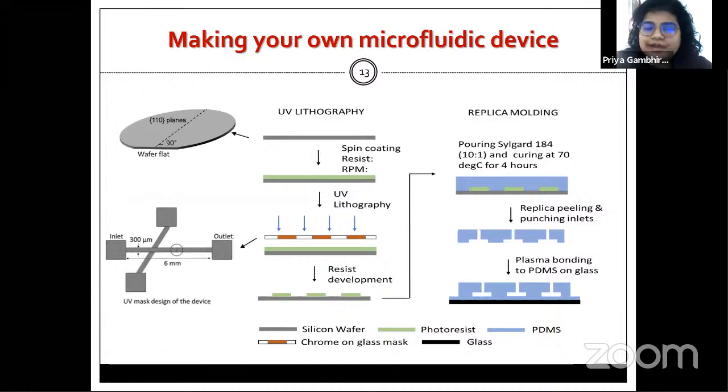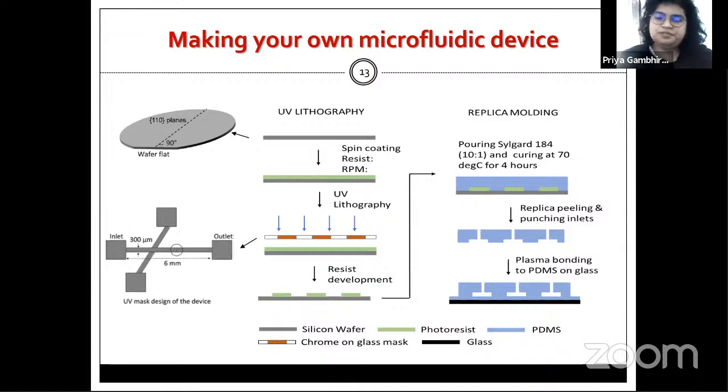Therefore, I read quite a bit of literature about what can be done, what the different microfabrication techniques are. And I realized that there's something called wet etching. What wet etching does is it's just plain potassium hydroxide, KOH, that is added to your wafer, and it dissolves part of the wafer. So you can have silicon oxide on top of your wafer, and it dissolves that silicon oxide. If you keep doing the wet etching for a longer time, it'll eat at particular planes of the silicon wafer longer.